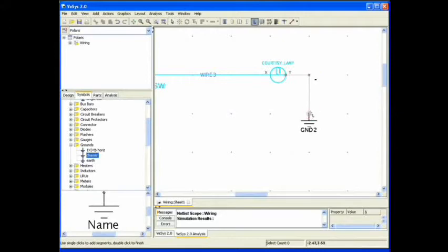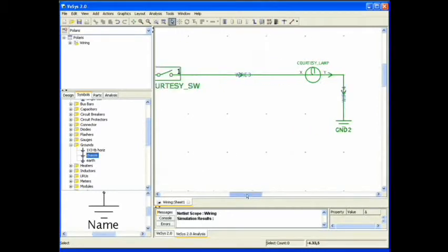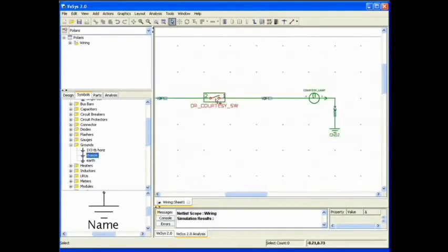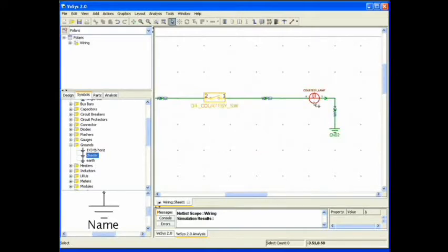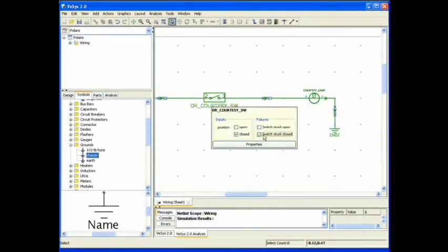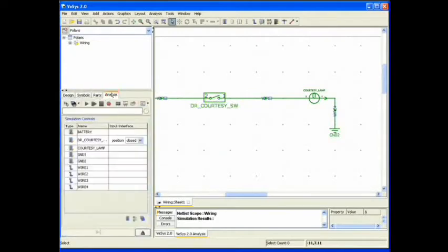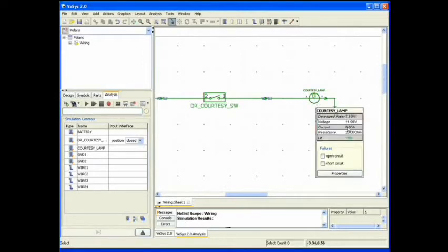Now the circuit becomes active, shown by the dark green color, indicating that current is flowing. We can also show the effects of component failures, such as stuck at false. Here, the switch is stuck closed. It is shown orange to indicate a problem. To analyze exact voltages and currents, we switch to numeric simulation, where the wire cross-sectional areas, resistances, and other parameters are brought into play. The simulator now shows detailed values for each of the devices and wires.